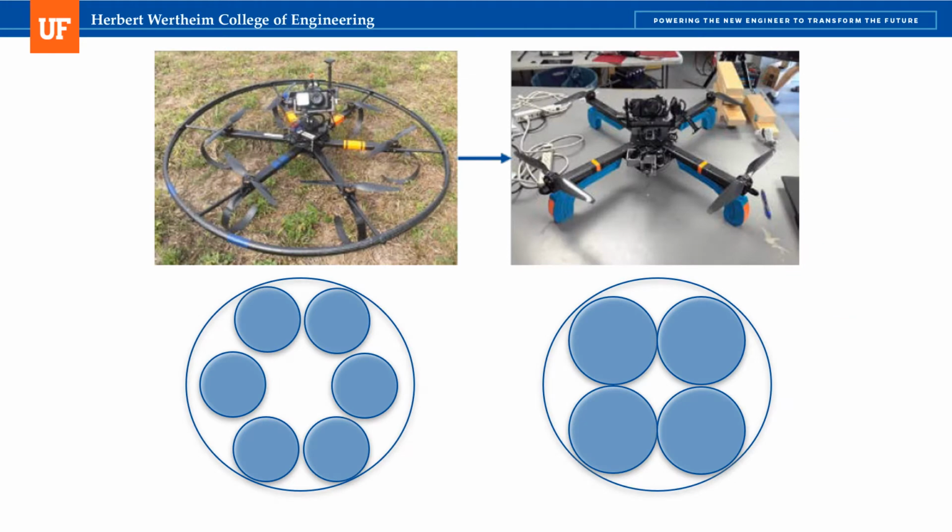This leads into our next figure, which is a quick demonstration on propeller efficiency. While more motors increase system redundancy, the overall efficiency is reduced since there is less propeller area in the same given diameter. The most efficient system is a single rotor, or helicopter.